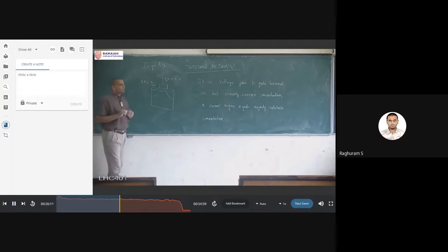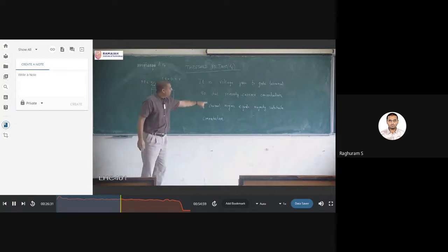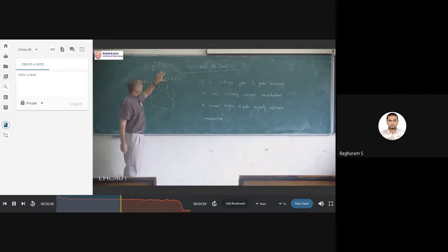So then the question now comes, if you keep increasing Vg, your minority carrier concentration is going to keep increasing, that is for sure. But when do you stop? When do you say, okay, enough, this much is enough for current? If I have this much amount of carrier concentration, I can get a good current in milliampere or microampere. That is the question that this statement is trying to answer. That is the voltage given to the gate terminal such that the number of, so this P sub, say it is 10 power 15 per centimeter cube.